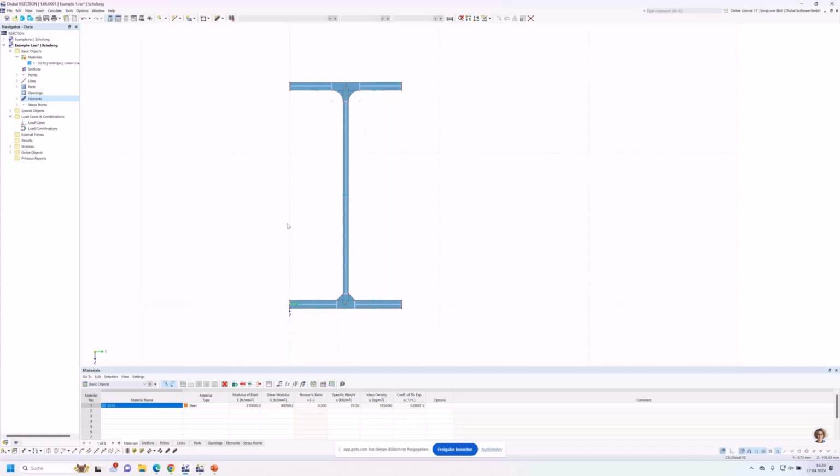The sub-panels that you can see here are automatically generated based on the standard selected in the base data dialog. These cannot be changed. If no elements are defined, a cross-section classification in RSECTION and the design modules of RFEM or RSTAB is not possible, and neither is a calculation of the effective cross-section possible. In the design add-ons, this cross-section is then designed according to cross-section class 3.